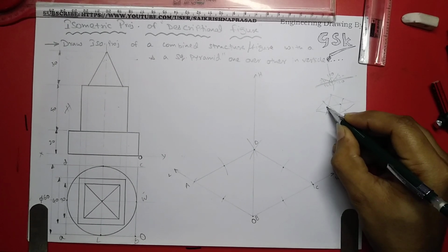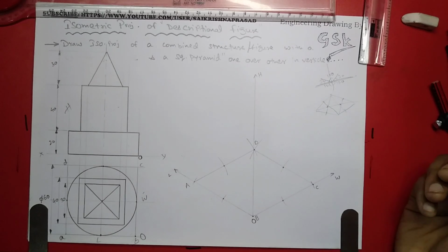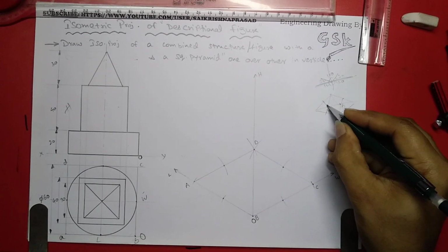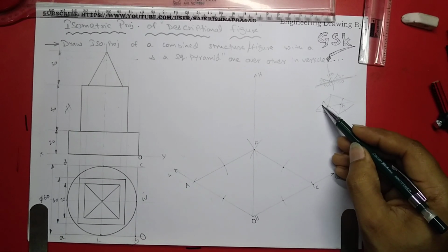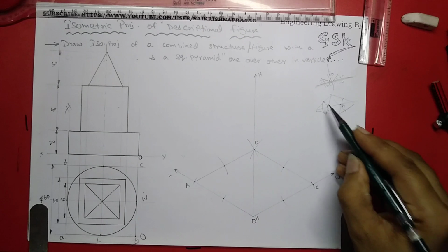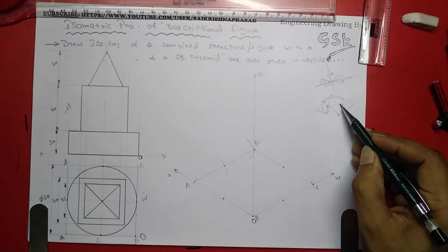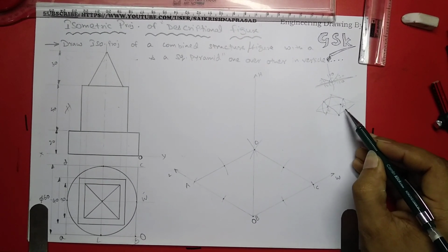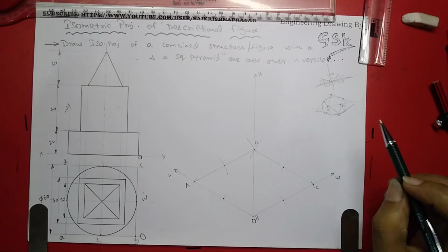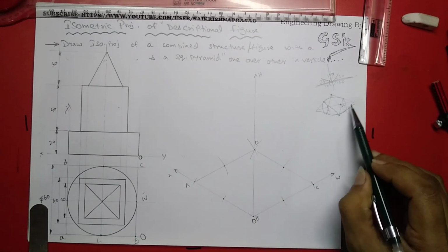You will be getting intersections over there, right? These are the focus points. From here, measure this distance and draw an arc, keeping F1 as center. Now this has center, measure this distance, arc. Next, this has center, measure this arc. Next, keeping this as center, measure this arc. So you have constructed the ellipse in this rhombus.